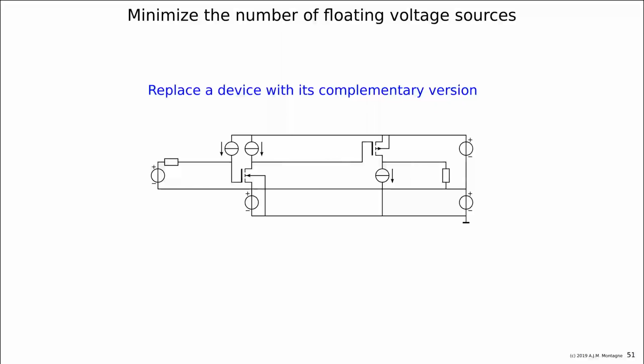Now, what we usually do is create a filter for the power supply so that high frequency changes are completely, let's say, blocked by the filter and cannot be injected into the signal path. But for low frequencies, you still have it, of course. A DC change of the voltage will have some effect, depending on the output impedance of the first stage.